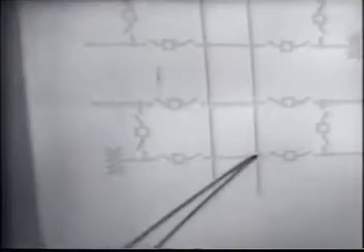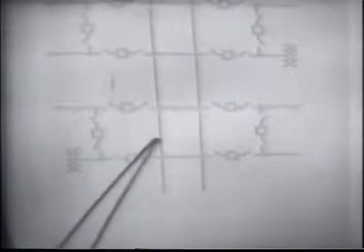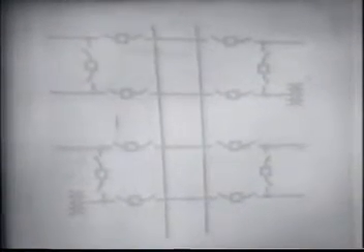The two buses of the breaker and a half scheme are connected together by these loops. You might say that a breaker and a half scheme is a series of ring buses connected together. This, of course, is more expensive than the ring bus or any of the other schemes that we have looked at. We've added, of course, the expense of one half a breaker for each circuit.